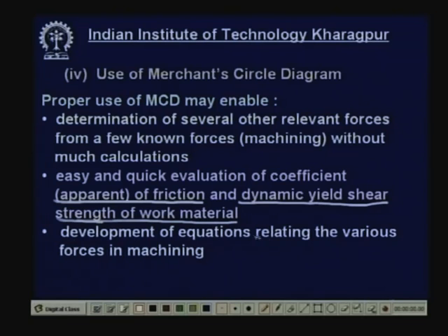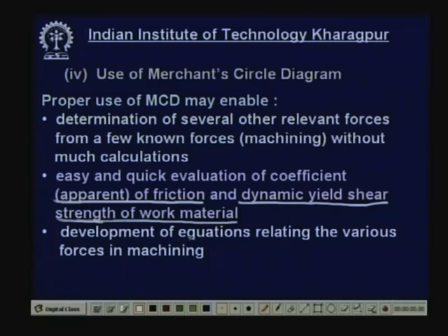Further, the development of equations relating the various forces in machining. Now, you know that some people are very strong in mathematics, they like to use equations and solve problems. Some people are very strong in graphics, the method of drawing and sketching, and slightly reluctant about using equations. For them, the Merchant circle diagram is very good, but some people may not like to draw the Merchant circle. They like to use equations, if available, for calculations or analysis or determination of other forces from the known forces like Pz, Pxy. Even if somebody wants to use only the equations to avoid the Merchant circle diagram, those equations will also be developed from the Merchant circle diagram. So, the Merchant circle diagram also helps in developing the equations which will be used to avoid the Merchant circle diagram, and these equations will be shown later on.